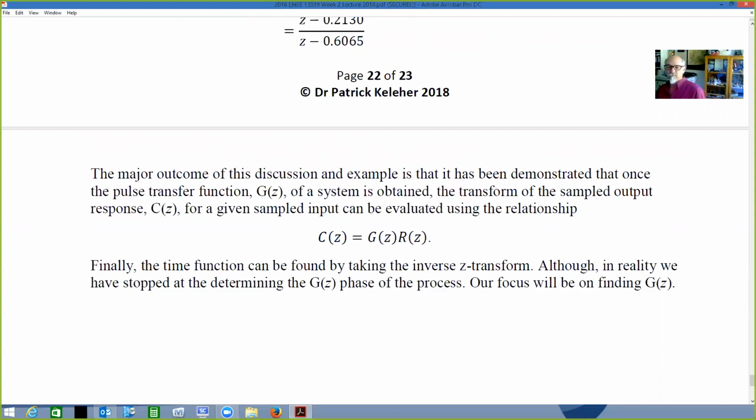All right. So again, from mathematical modeling of electrical systems using the fundamental electrical principles, circuit analysis through Kirchhoff's laws and Ohm's laws, for mechanical systems looking at friction, damping, inertial masses, all those fundamental things come into practice, rotational things as well. And ultimately what we're trying to do is find the transfer function.